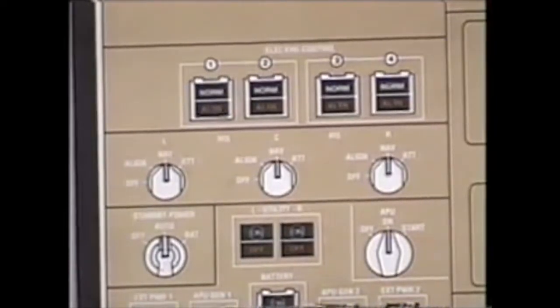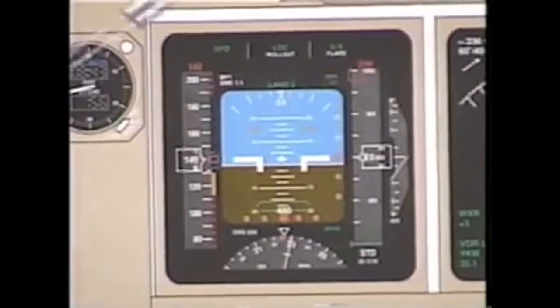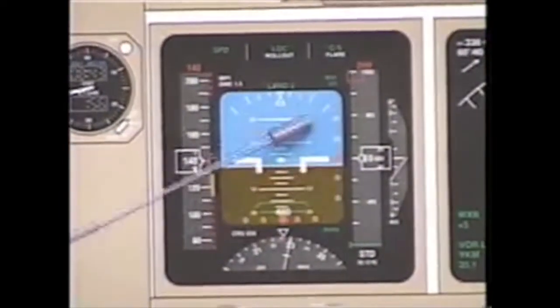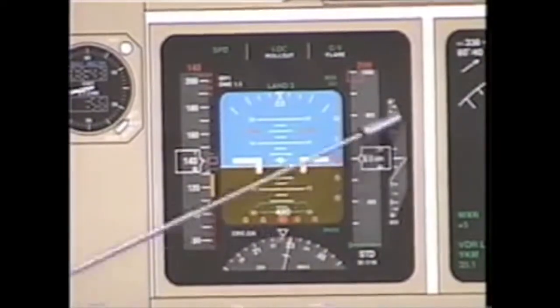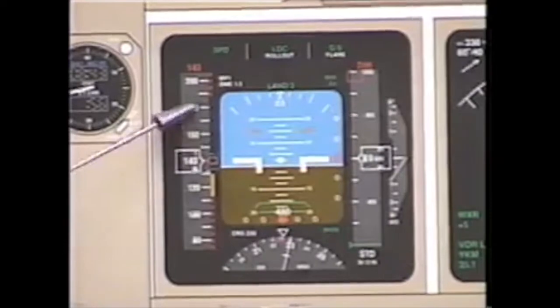IRSs do not navigate. The FMCs, left and right, are responsible for navigation. The IRS provides input to the FMCs for that purpose. To go from off to nav, a full alignment takes approximately 10 minutes, provided position is loaded. With a fully aligned IRS in the nav mode, it will generate 4 items on your PFD. The IRS will generate the attitude picture and the IRS heading. The accelerometer portions of your IRS will give you vertical speed and the green airspeed trend arrow.